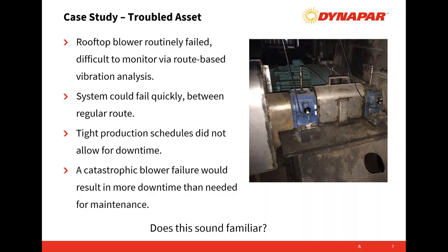Yeah. So in this case, I'll flash back through the pictures. This is a stud mount application, and you can see the cast iron or aluminum bearing blocks were drilled and tapped, and then a quarter 28 fine thread, which is the common convention for the US, was used to attach that sensor on the tangential portion of the bearing. And as Derek's indicating, on the sensors themselves we have an XYZ coordinate plane label, so you have an indication visually as to how things are mounted.